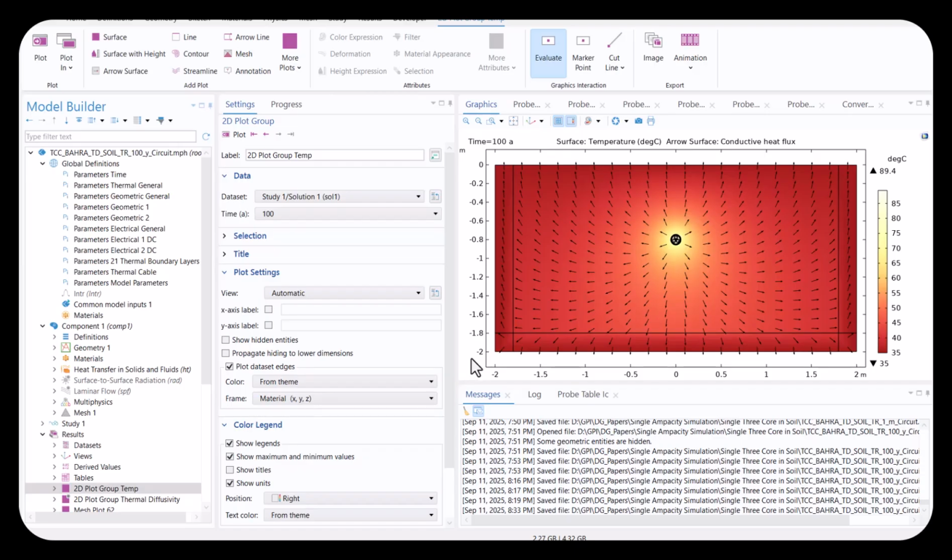Here is the COMSOL Multiphysics FEM model. I use COMSOL Multiphysics because I like that it is designed for multiphysics and I just need to create the geometry one time, assign the materials one time, and create the mesh once for as many multiphysics couplings as I would like to include in the model. Unlike other FEM software, you would need to create the geometry, assign the materials, and set up the coupling using some platform or something, and it involves many different project files. With multiphysics it is one project file, everything coupled together, and the coupling is actually automated.